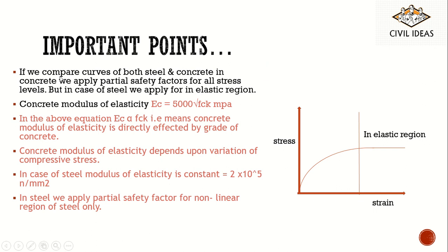Now, there are some important points you should remember. If you compare the curves of both steel and concrete, in concrete we apply partial safety factors at all stress levels. But in the case of steel, we apply it in the elastic region only.